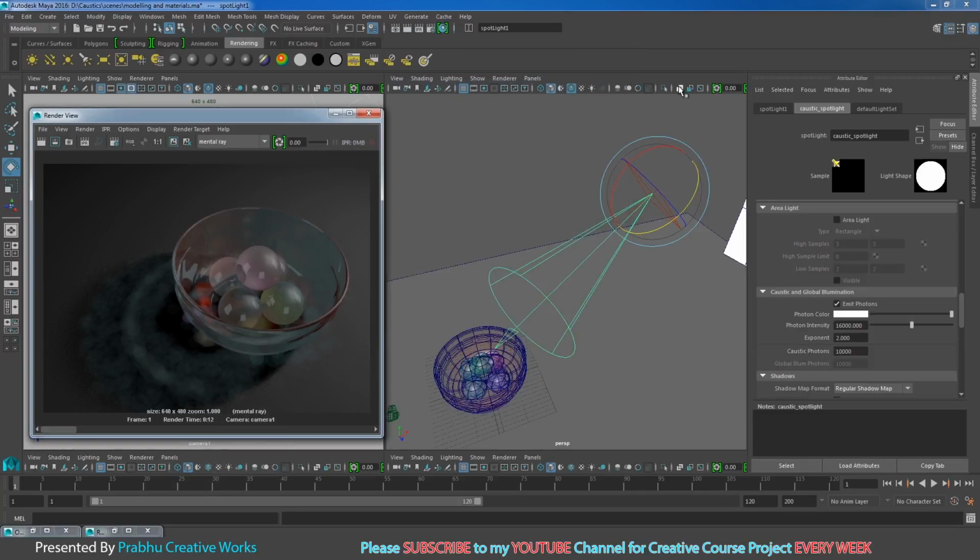So I will select my spotlight and go to caustics and global illumination. Here we have caustic photons. I will increase to 20,000 photons and press enter. Keep this image for comparison and click render again. See here it is a little bit sharper in our caustic photons.